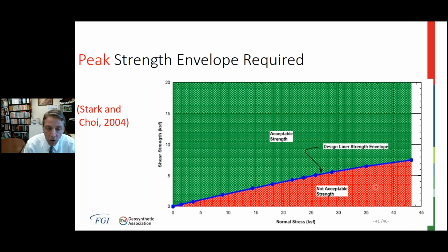No, there's not a firm rule like 4-to-1, 3-to-1, 2-to-1. It really depends on the interface strength. Having said that, there's at least one state now that mandates no final slope will be steeper than 4-to-1, 4 horizontal to 1 vertical, because they've experienced some slope stability failures and the state has had to sort of remediate the site. So if we don't do a better job, there may be rigid requirements or mandates of allowable slopes if we don't do a better job. But right now, they're not.